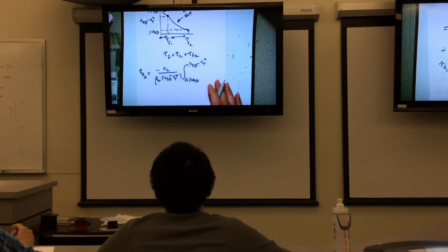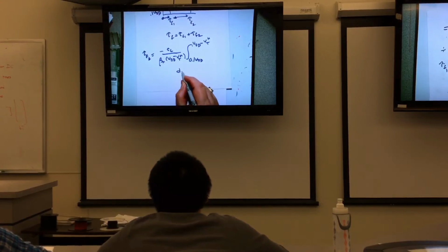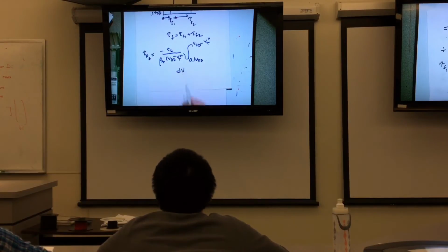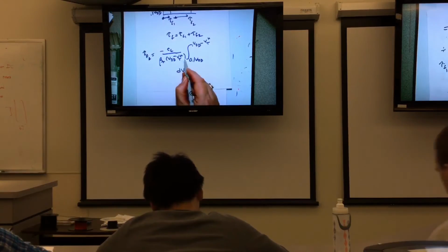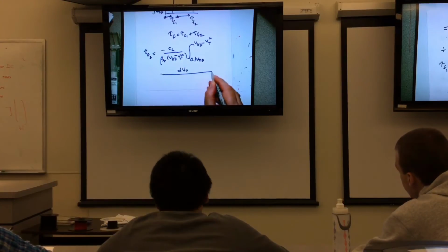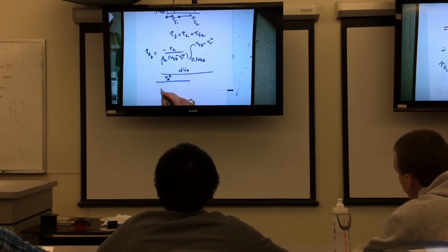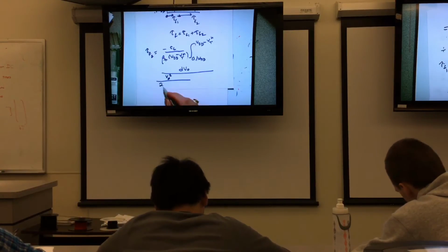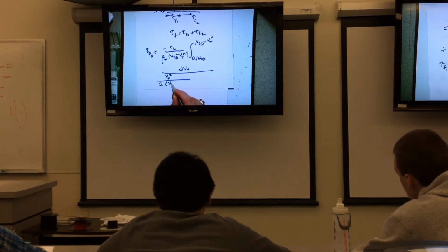And then the body of the integrand is going to have that active IDS expression in it, but I've already divided it by VDD minus V threshold N, that guy out in front. That's going to be important. So there's our V out, and we have V out squared divided by, there's the 2 that we would normally expect to find for the active IDS.